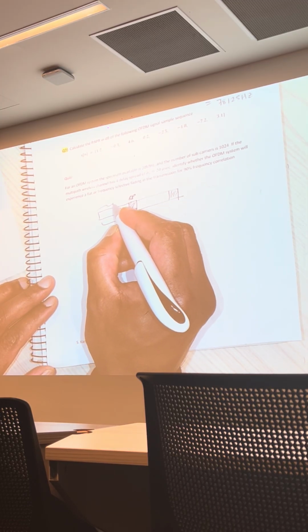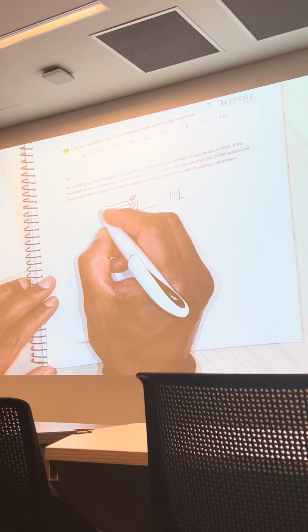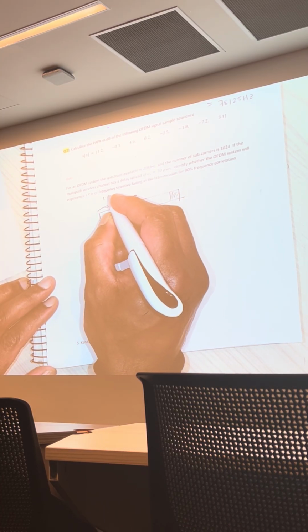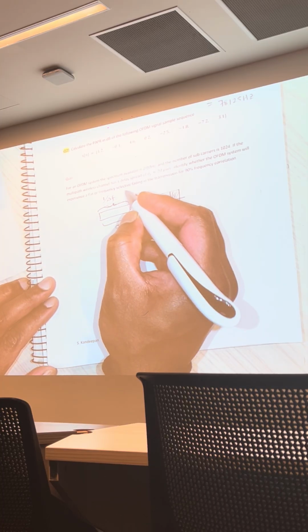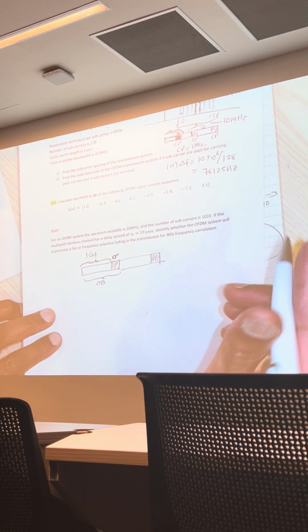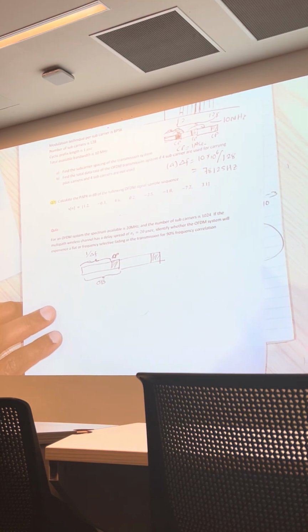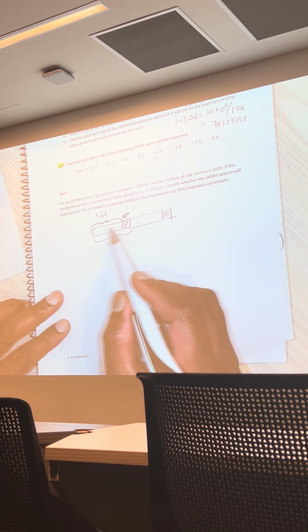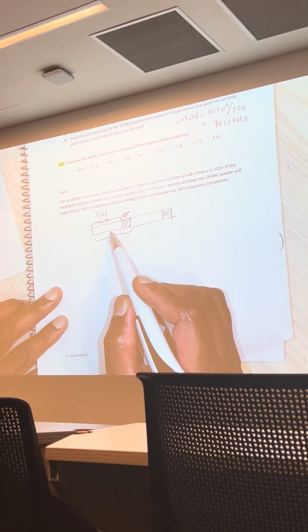And this period here is 1 on delta F. What is delta F? Delta F is the subcarrier spacing, right? Why is this length 1 on delta F? Because that's the theory: if you don't have that as 1 on delta F, or multiples of 1 on delta F, then you will not achieve something called orthogonality.